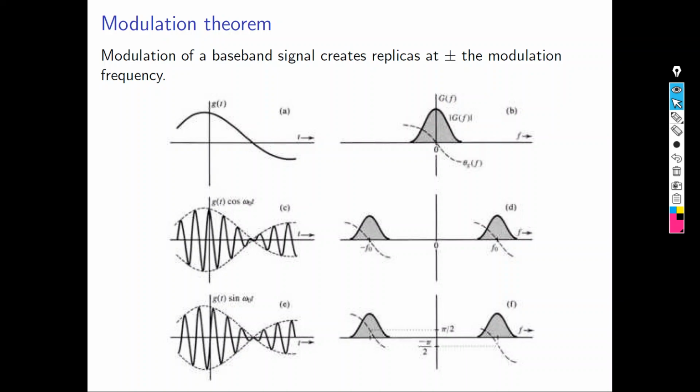Second, the frequency is so low, so there is no such antenna that can match the lambda. Physical size of the antenna will be so big that you cannot design or deal with. To avoid these two problems, you shift it to an appropriate frequency where you will be able to design the antenna and you will be able to share your information only with the intended user.